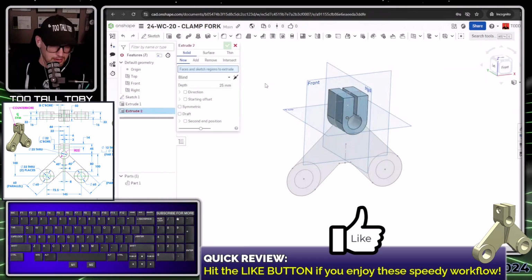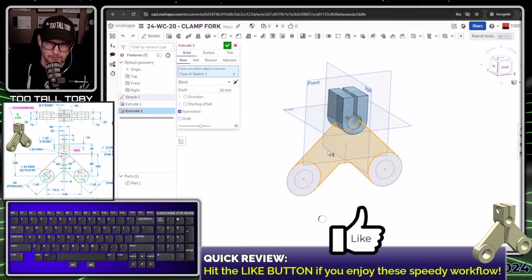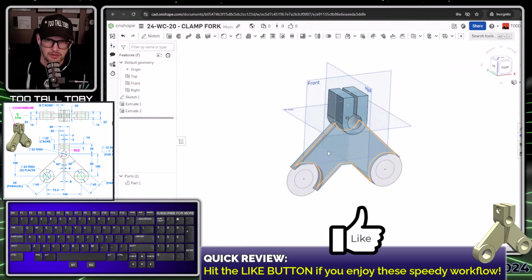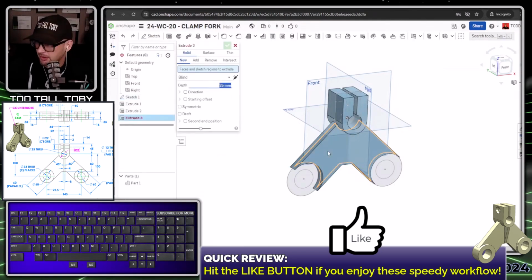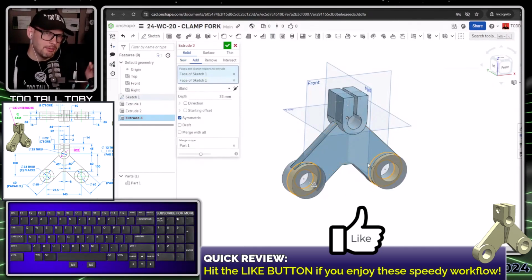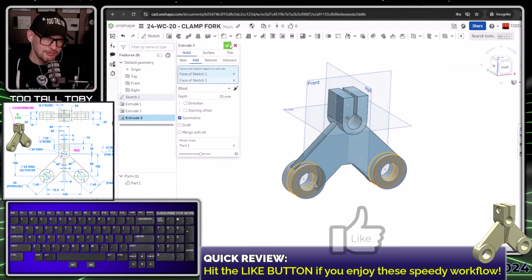Shift enter, tab, 16, tab, space. And then I'm going to pick this region. Preview's updating here. And then I'm going to shift enter, and then tab, 33, tab, space, and then I'm going to pick these regions here. So you can see how quickly we were able to go from just having our layout sketch to having multiple features if we learned about that shift enter trick.